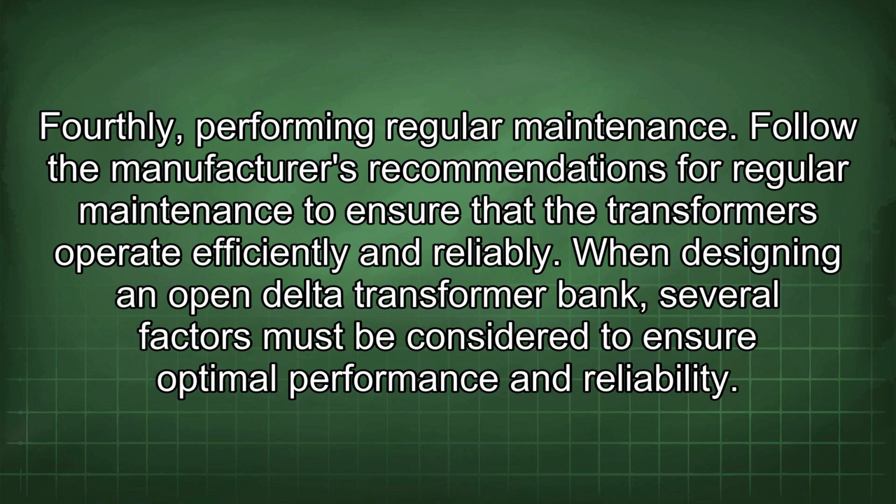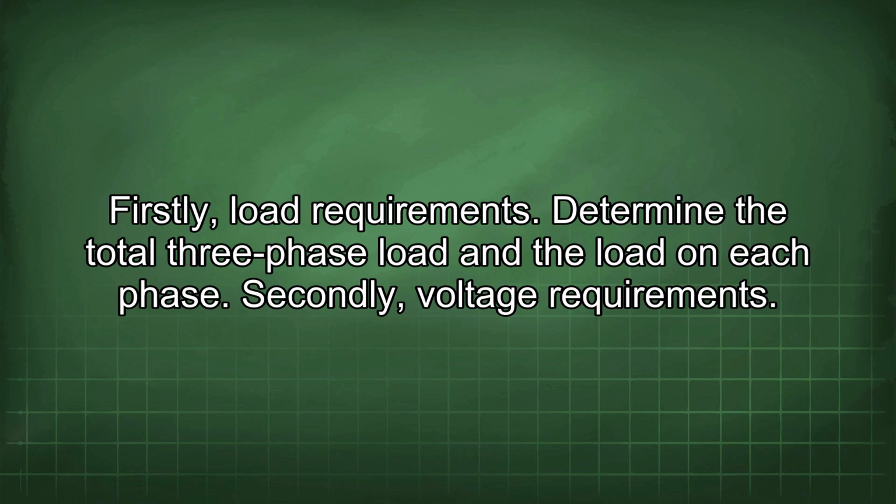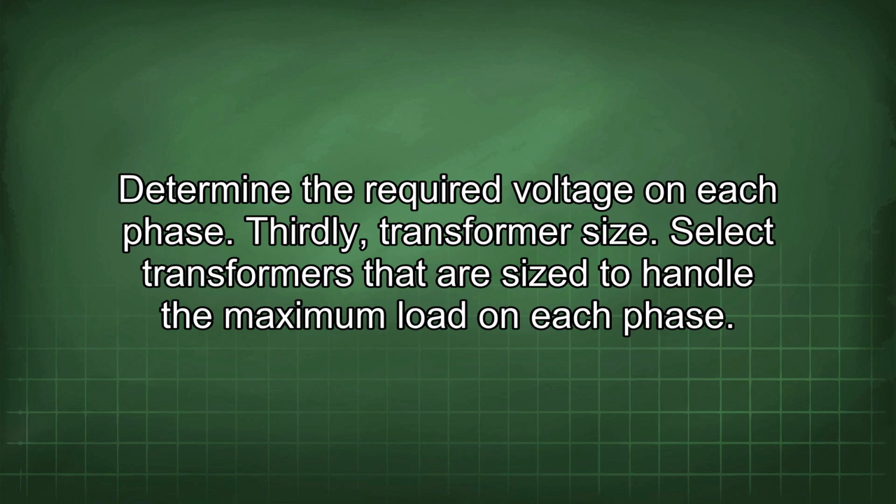When designing an open delta transformer bank, several factors must be considered to ensure optimal performance and reliability. Firstly, load requirements. Determine the total three-phase load and the load on each phase. Secondly, voltage requirement. Determine the required voltage on each phase. Thirdly, transformer size. Select transformers that are sized to handle the maximum load on each phase.